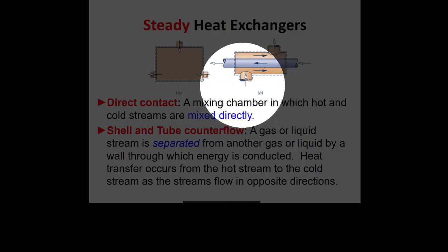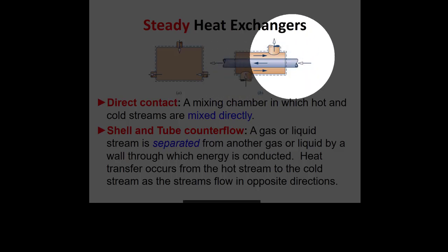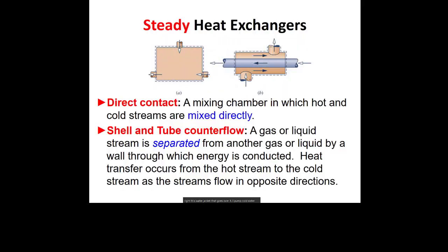I pump cold water through the shell, hot engine oil through the tube. And what happens is that oil is going to get cooler and the water is going to get hotter. Right? Just like we talked about, the radiator is also kind of like this, where your flow doesn't mix together directly. You have your radiator fluid, which is getting cooler because the air that's flowing over those fins is getting hotter. So there's heat being transferred from the radiator fluid to the air.